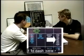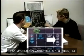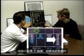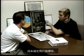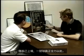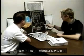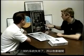What about 1 FD dash? 1 FD dash indicates that, again, the captain's flight director is on, is being commanded by flight director 1, but the first officer's flight director has not been selected on. 1 FD1? The captain is on, and number 1's commanding his system. The first officer's is on. Number 2 system is inoperative, so he's going off of